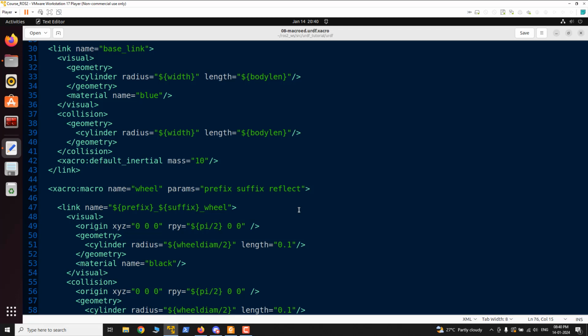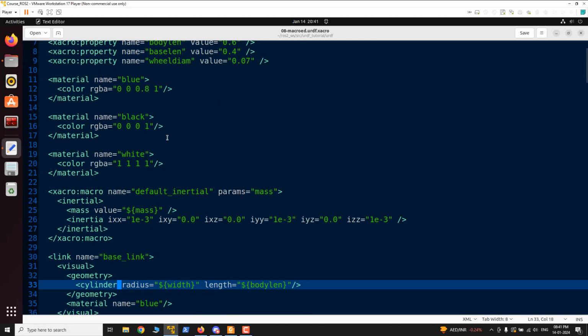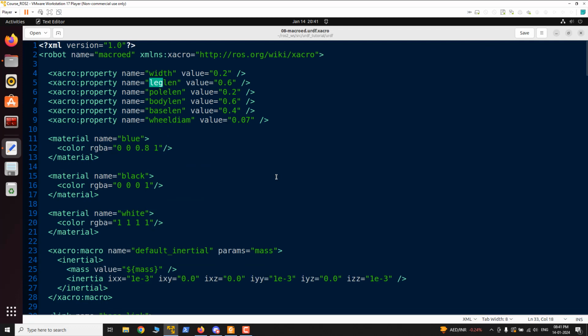I can explain. If you are working on SolidWorks or Fusion 360, some plugins convert into URDF. So basically the objective is to get the URDF, but if you are manually creating a robot without any plugins, you are simply exporting the links and you can use them in the geometry. If you're completely customizing or building it from scratch, then the Xacro representation will be good. But if you're converting using a plugin, some plugins will directly give the URDF, so we don't need to worry about it. If the converted URDF is good for you, then you don't need to touch it.